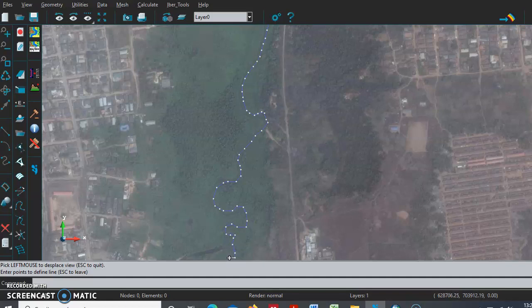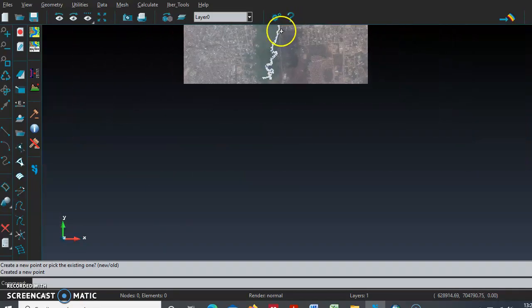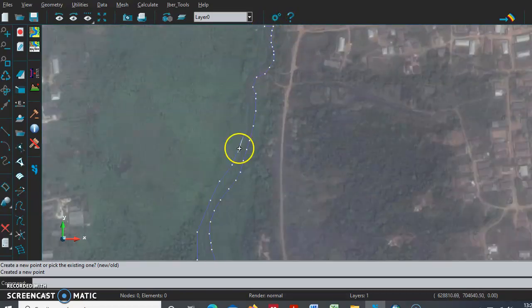And the place where you want to have the outflow, you have to do another perpendicular line from one bank to another bank. Like that one. And I go again. I will have to close a polygon. Don't worry about this, later I'll tell you what that is. You have to be like this, more or less. Don't worry if it is not exact. It depends on the resolution. If you want to work with all the river, you will have to do it like this, not very properly, but more or less.